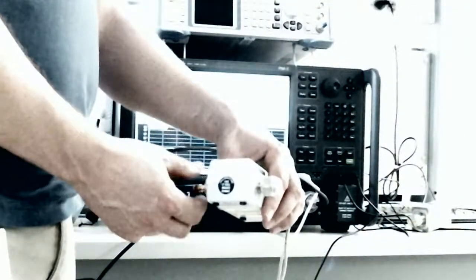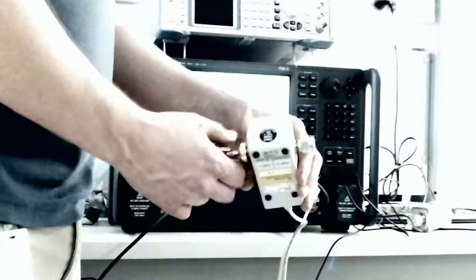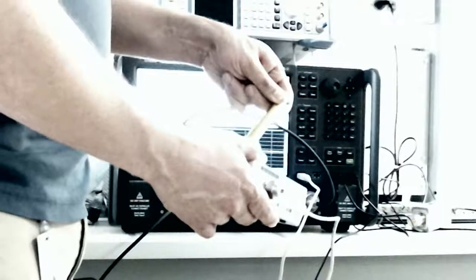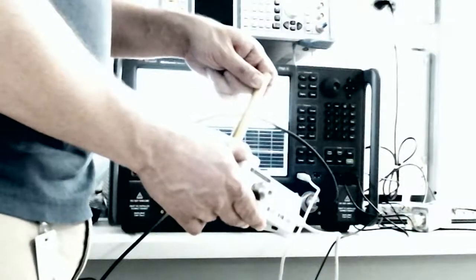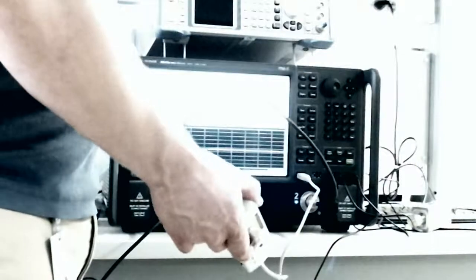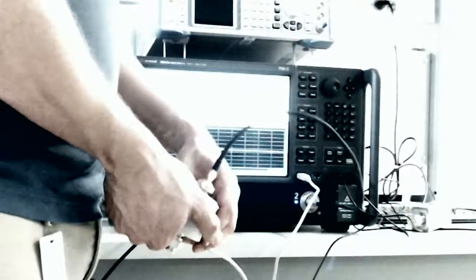So for noise figure measurements, how familiar are you guys with noise figure measurements, just out of curiosity? Not at all? Okay. Typically when you're measuring noise figure, you're either looking at a converter or an LNA or part of an LNA and converter chain, right? Sometimes you may look at the noise figure of an antenna, which is maybe something you guys have heard of, but that's a little bit of a different measurement. You don't typically do that using a network analyzer, and I'll talk a little bit about why.